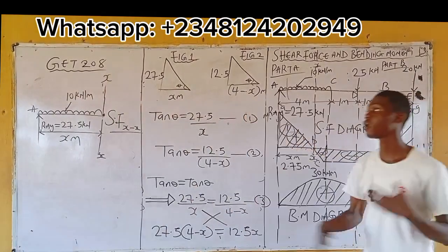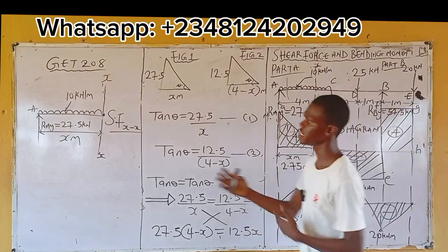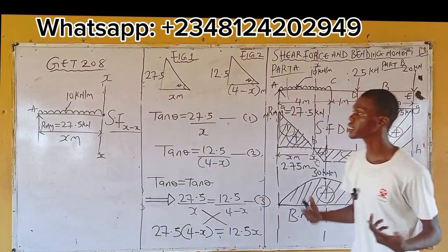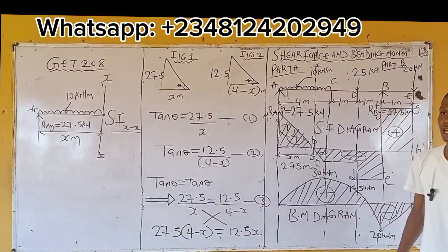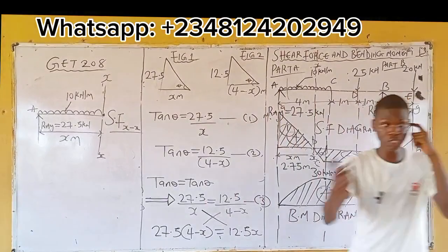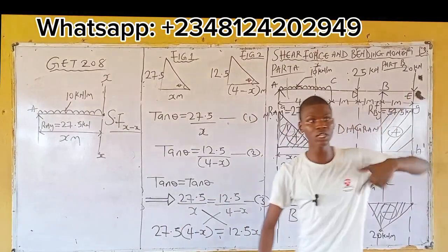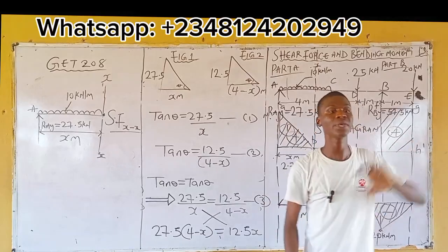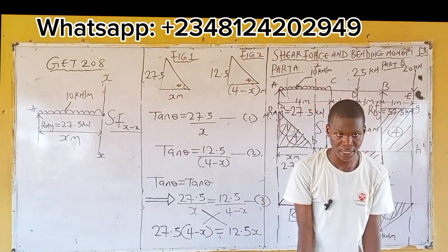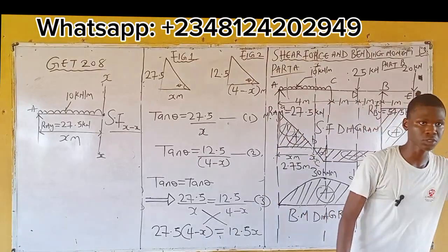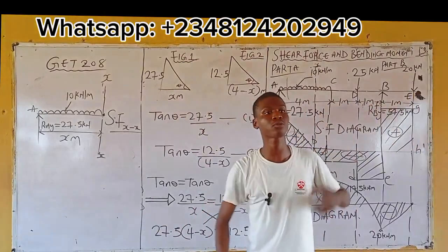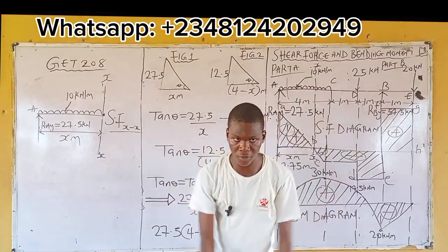Now, when we want to calculate shear force, we simply say that I'm calculating the shear force value at each point on my beam. And how do I get this value? You calculate shear force value twice, right? And you know the condition. The first value is the algebraic sum of forces behind the point you want to calculate. The second value is what you've calculated plus the force you have on that point.